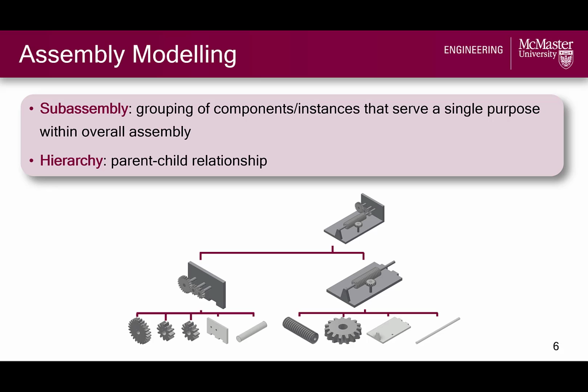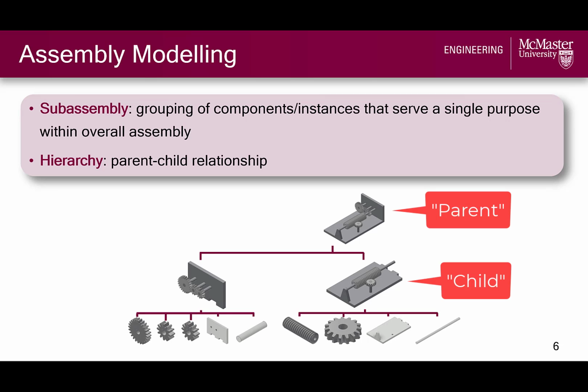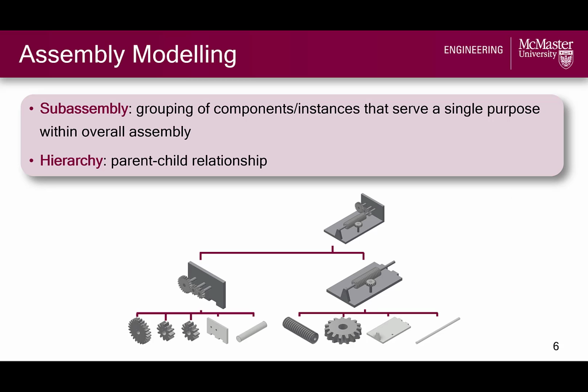For instance, the overall assembly is the parent to the subassemblies, and the subassemblies are considered its children, and these relationships determine how constraint relationships between components will be represented. We won't worry about this too much, but I do have to define what I mean by constraint relationships between components in the context of assembly modeling. Before we go into assembly constraints, let's review constraints in the context of solid modeling.